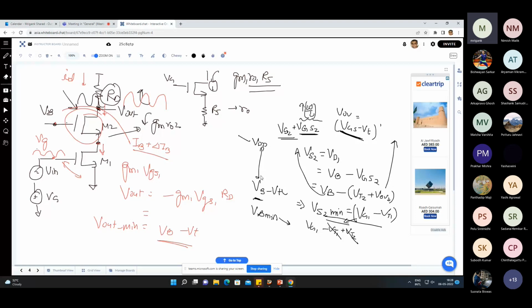So once you are designing the circuit, just looking at the simulation results, you will see what is the DC point coming at which point, what is the DC voltage, and you can see that by changing what device I can bring all the transistors in saturation, or if I change certain voltage levels, which transistors will enter into triode. Those things should become clear just by looking at the circuit and the simulation results based on the concept that you are studying here. So these equations are to help us in understanding. These equations should be running in our mind. Mentally, we should be able to do it.